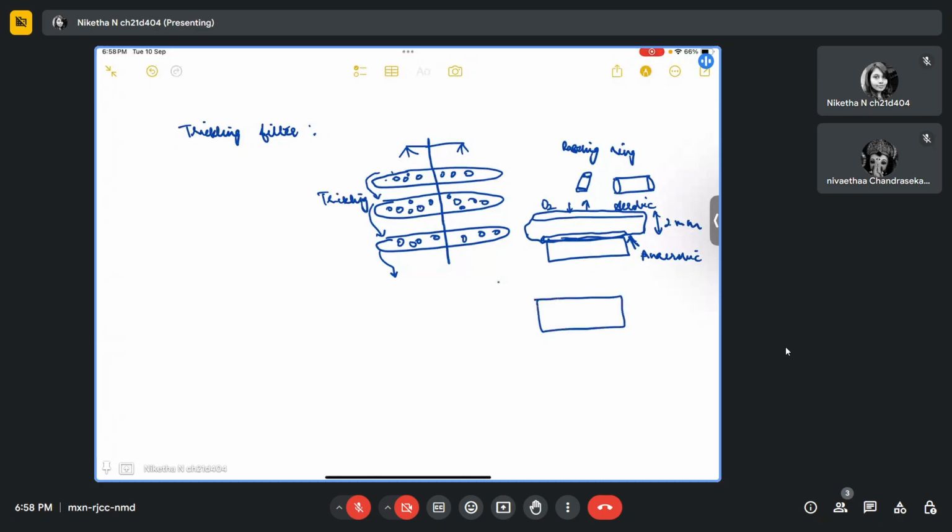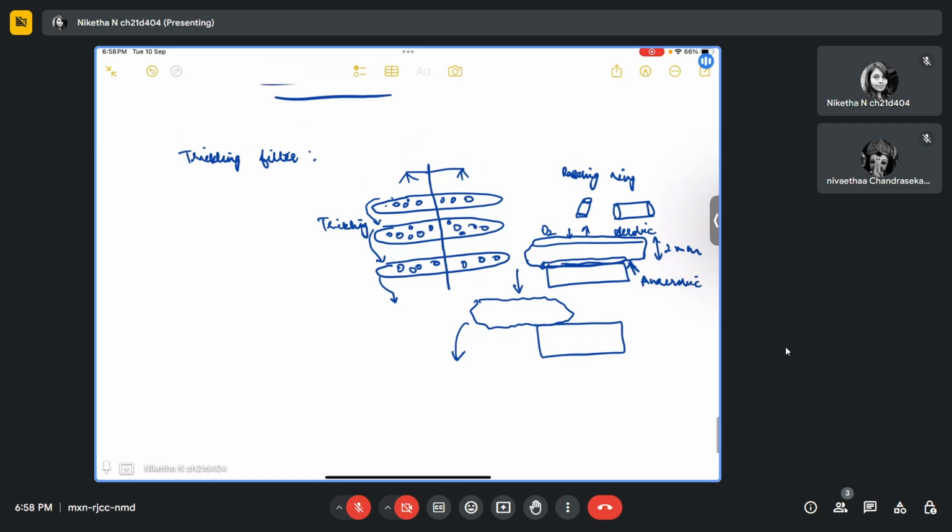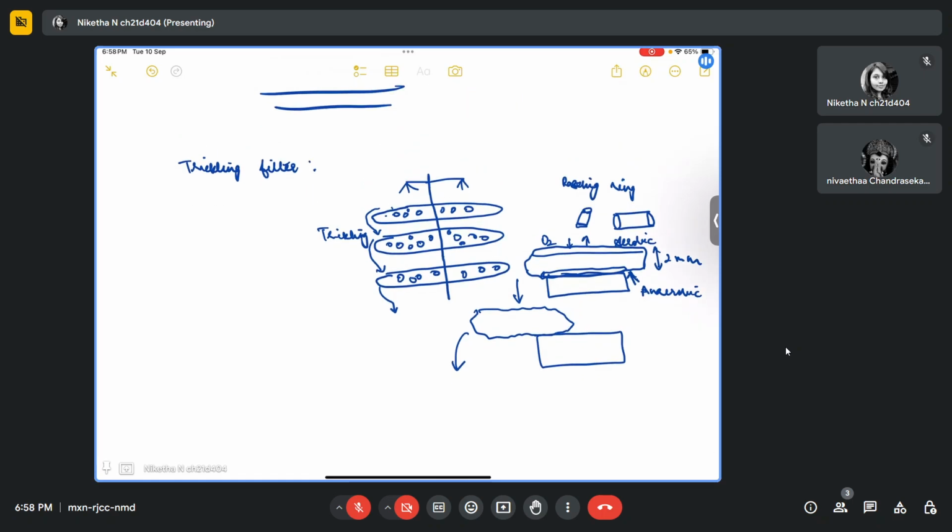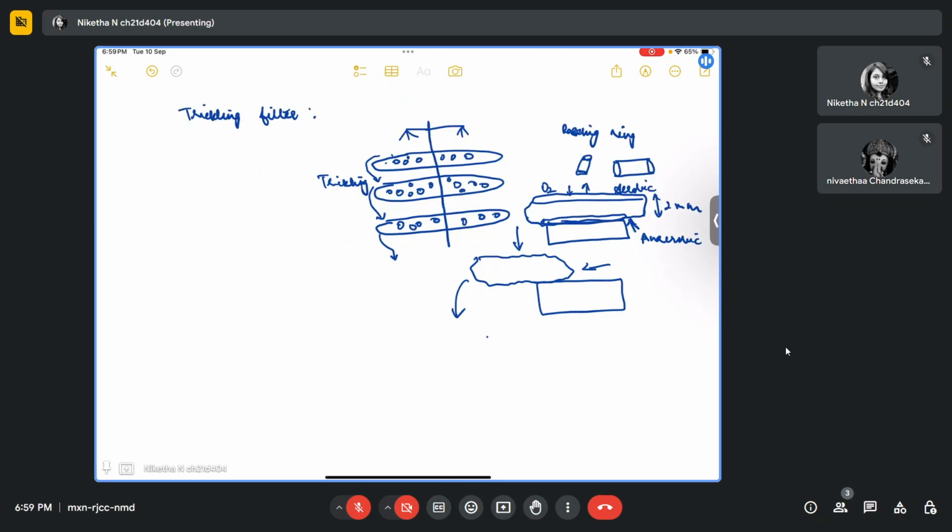So when you have a very thick slime layer, slowly it will get detached and it will fall down. This process of falling down will be instigated even more by the water that is coming from the top. If the wastewater is coming at a certain speed, then that is going to instigate this process of the slime layer passing down and falling down. So this process of the slime layer falling down is called sloughing.